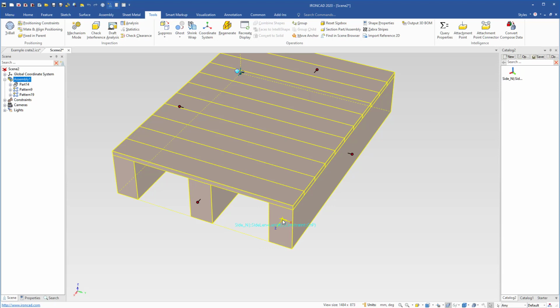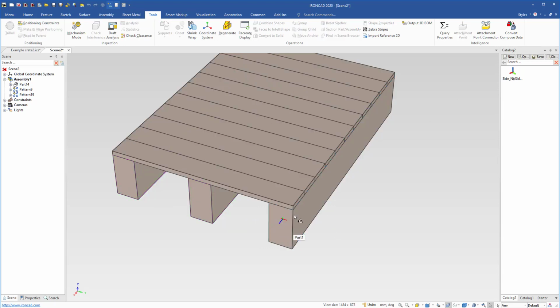I can then just use my tri-ball when I select down to my assembly, select that attachment point, there we go, select our assembly, select that attachment point, turn your tri-ball on, and then we can just move it up to this point and just rotate it and orient it the way we want. We want it to go up, and we want it to turn inwards 90 degrees.